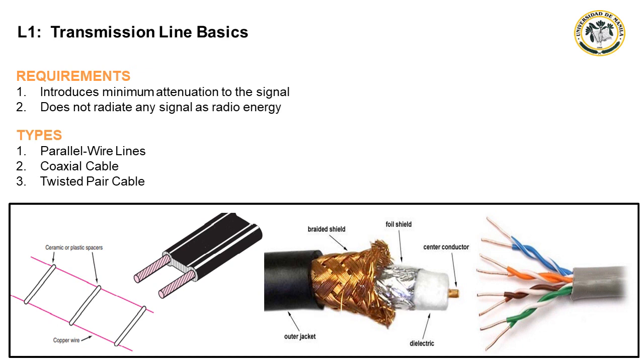It is generally known as unshielded twisted pair or UTP cable. There are many grades of twisted pair cable for handling low frequency audio or high frequency pulses. The size of the wire, type of insulation, and tightness of the twist determine the characteristics. It is available with an overall braid shield and is called shielded twisted pair cable.